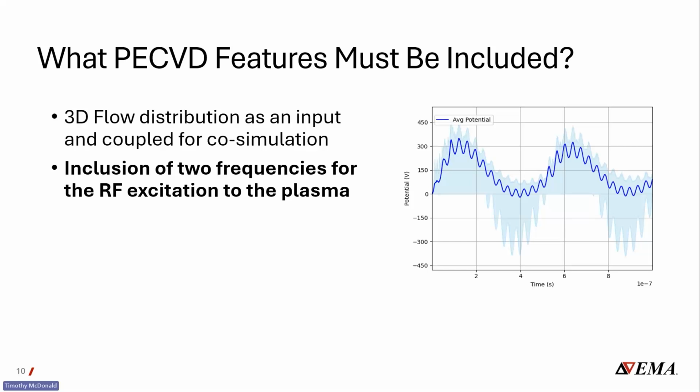The third is impact on the film properties. Film density, stress, and hydrogen content in PECVD layers all depend on the energy and flux of ions striking the surface. If you have too much energy, you could cause damage, re-sputtering, or stress. Too little energy can lead to porous, low-quality films. Dual frequency is what lets engineers tune precisely, but only if they understand, ideally via modeling, how both sources shape